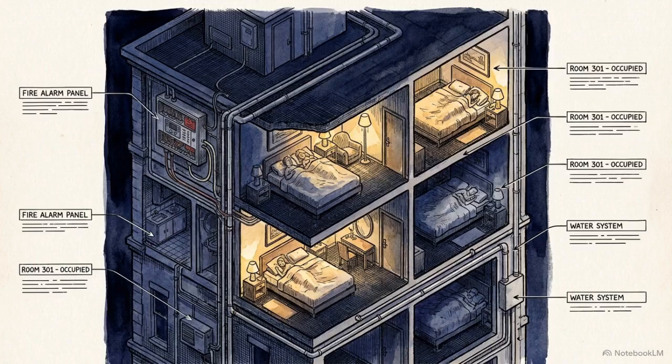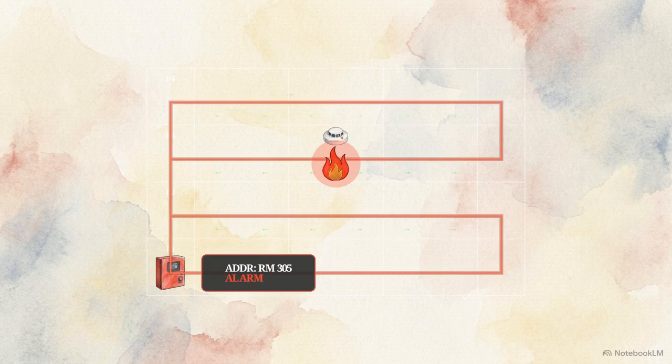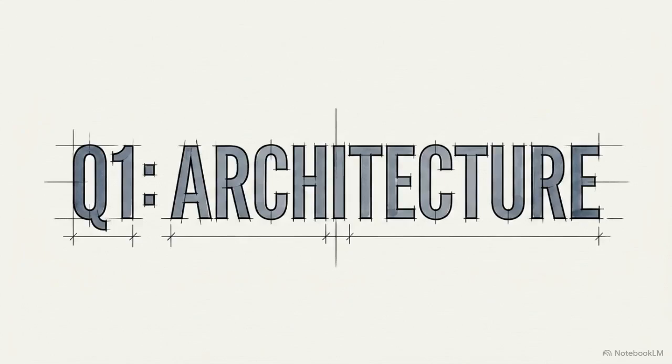For sprawling hospitality structures like hotels, the primary threat is navigating hundreds of sleeping occupants. These require highly automated, fully addressable networks to pinpoint exact room origins and execute complex phased evacuation protocols without inducing panic. There is no universal safety solution off the shelf. The operating environment dictates the exact system design. Let's lock in the technical specifics.